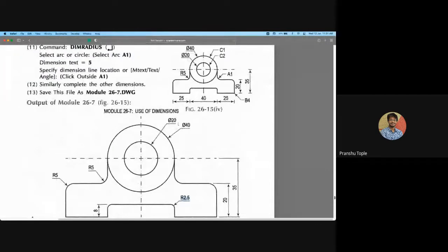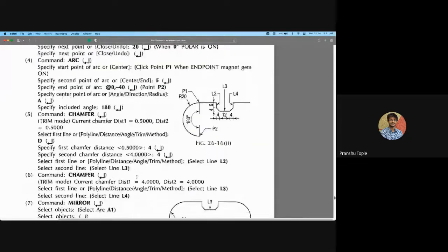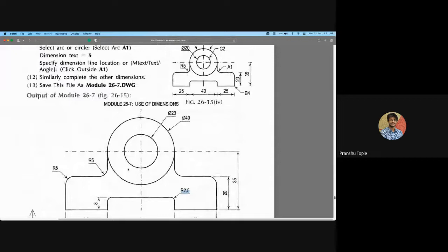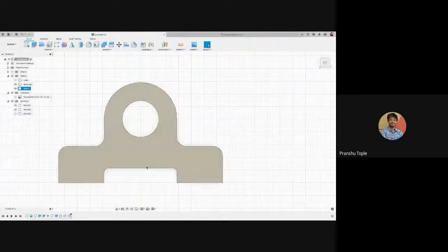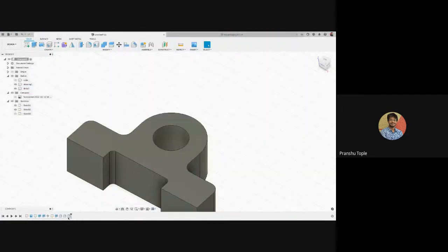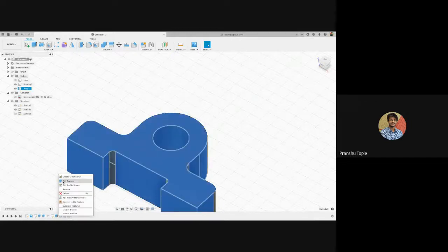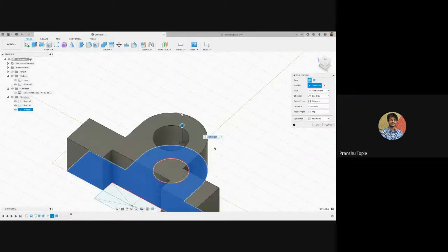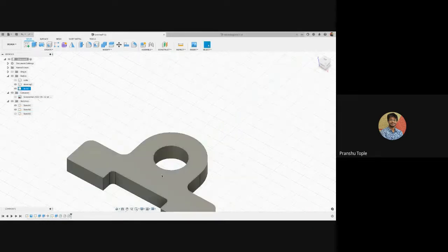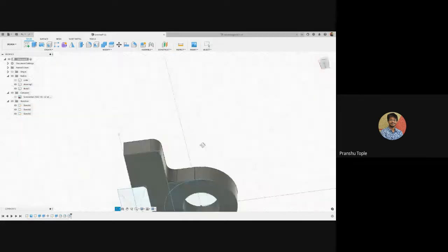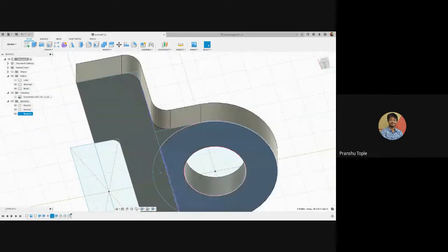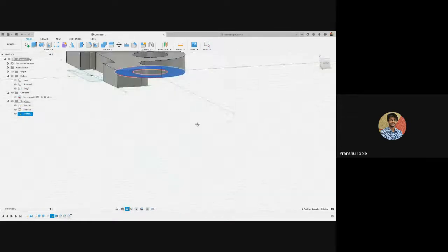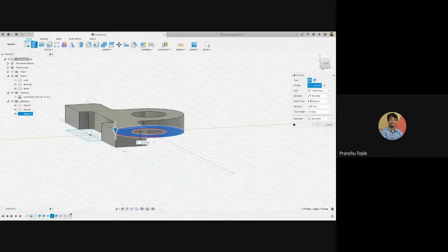Understood? Now they have defined this circle like a separate circle. So I guess what should be the case is this should be more extruded than the below part. If you want to do that, you can do that. So here when I extruded, I would edit the feature. Instead of 25, I will just do 10, I guess. Yes. And again, I will enable the sketch. In this sketch, I will select the circle that I want. And I will extrude it even further.